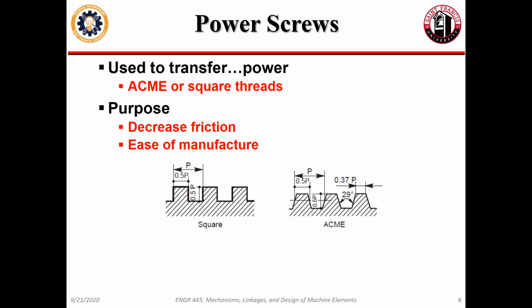They're just a little bit tapered. In theory, it should be a 14.5 degree angle from the vertical there. So you look at the profile of an individual tooth, kind of like it's showing up on the thing.